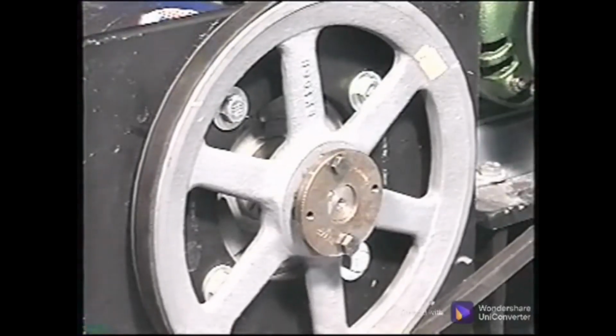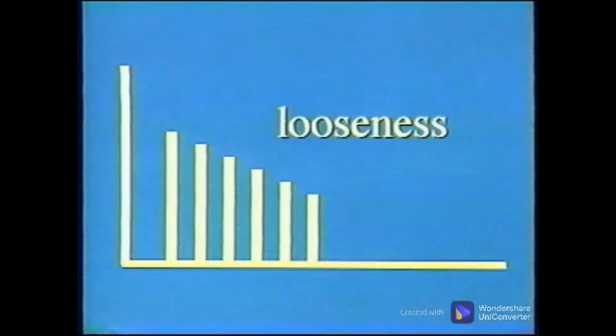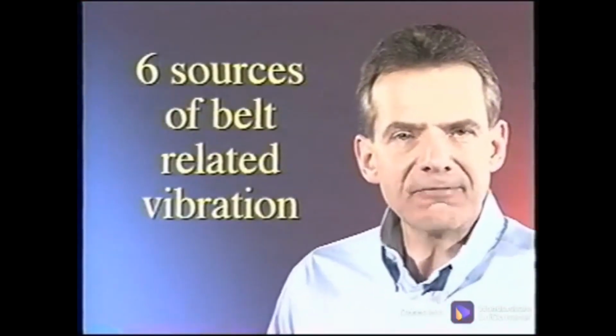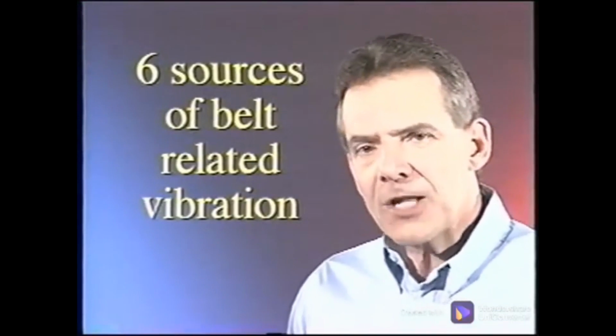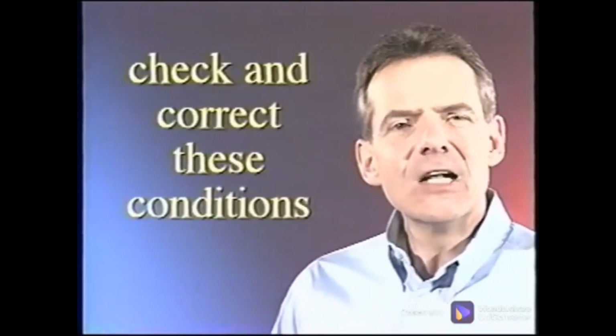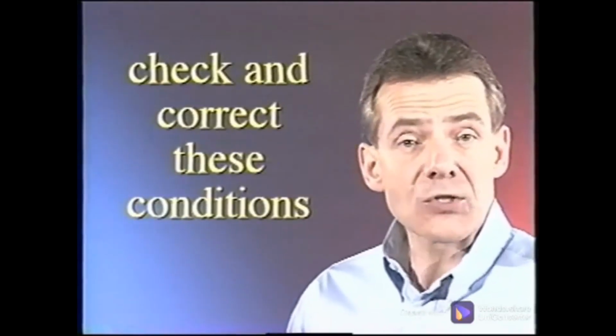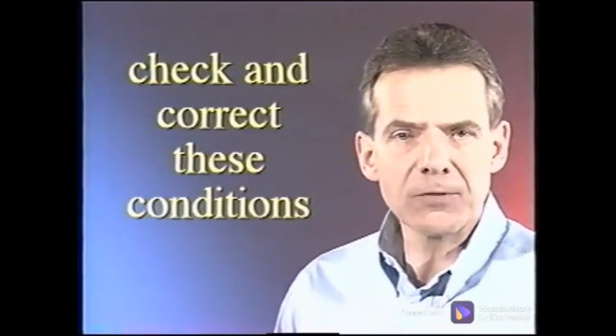Another source of belt-related vibration is a sheave loose on the shaft. Even when the sheave is keyed on the shaft, it can be loose and generate substantial vibration. The spectral data will have shaft speed harmonics similar to other mechanical looseness conditions. When these 6 sources of belt-related vibration are corrected, your belt drives will run smooth and quiet with a much higher efficiency. The next section illustrates how to check for and correct these conditions while installing belts to eliminate belt-driven problems.